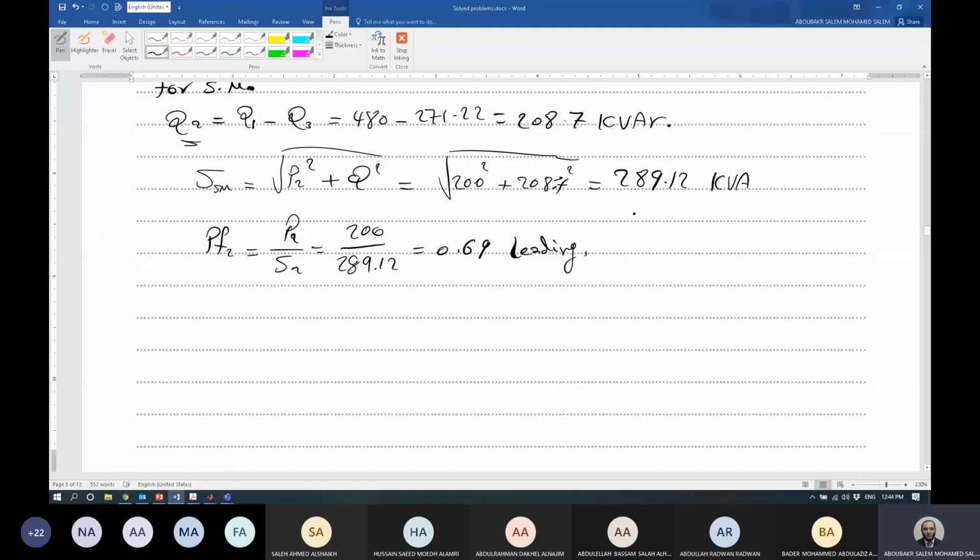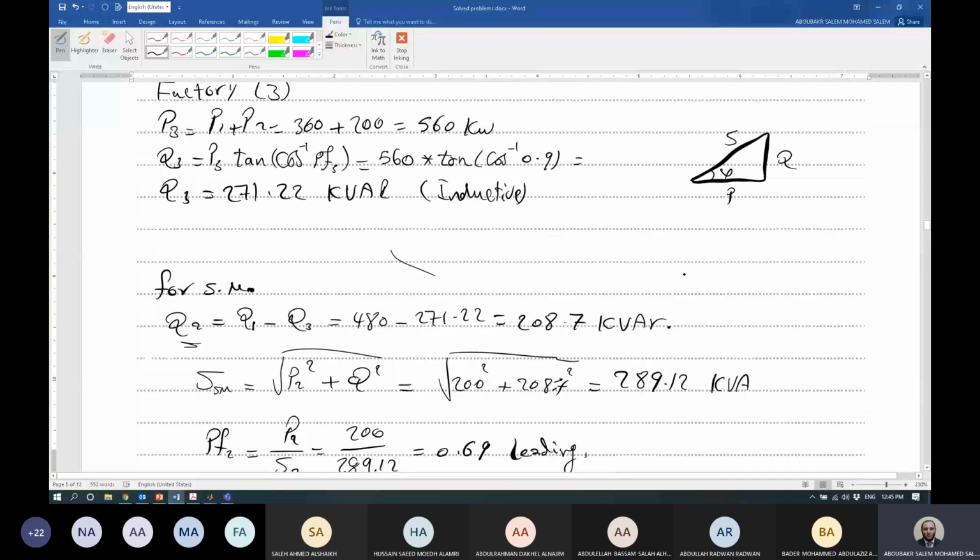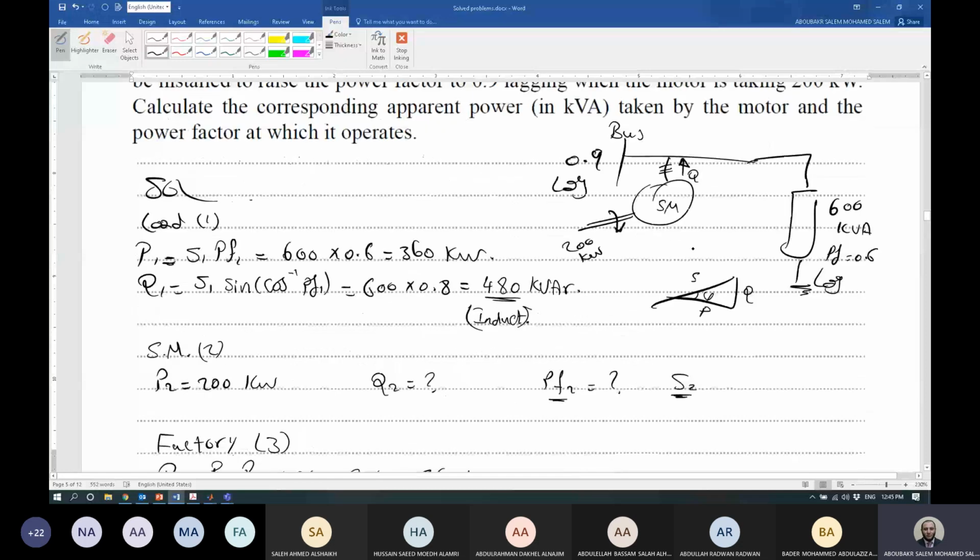Right. Okay. If we can supply more reactive power, why shouldn't we supply it? What I see, you should operate the motor at full capacity, to draw the rated kilovolt ampere and deliver the maximum possible amount of reactive power, but without overloading the motor. Without overloading means to only operate at S rated.